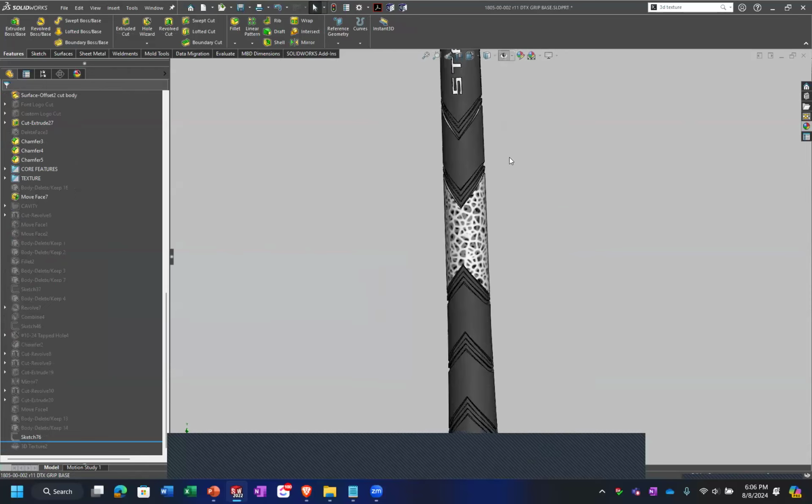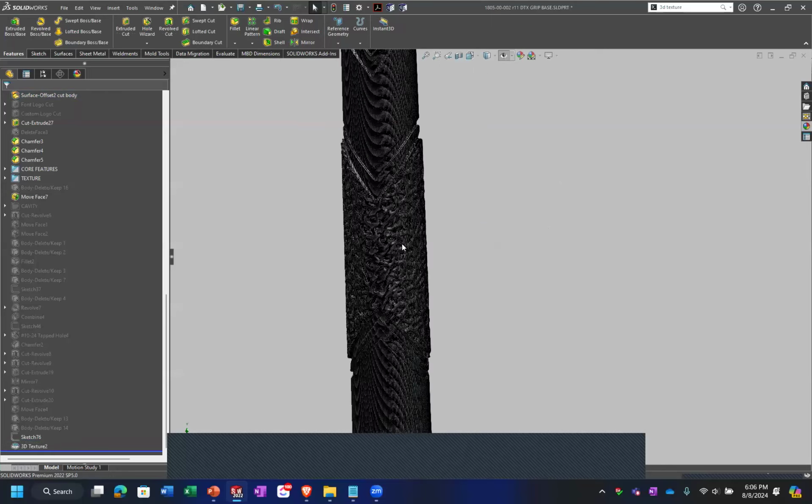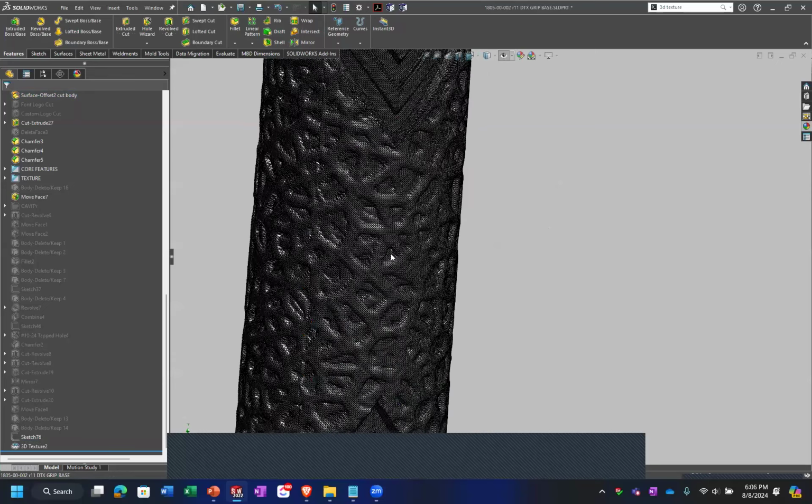It's watertight to where you can print from it, right? Correct. It should be printable. Now, don't get me wrong, sometimes when you import it, it might say there's a micro mini face missing or something, but typically you can auto heal that and it'll fill whatever tiny gap it is. Technically, it should be watertight, and it does a pretty good job. We've done this pretty regularly with different types of models and had good results.